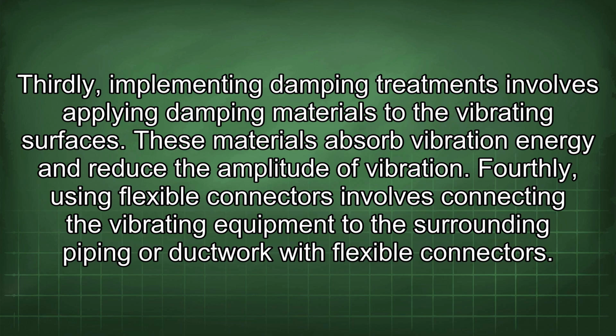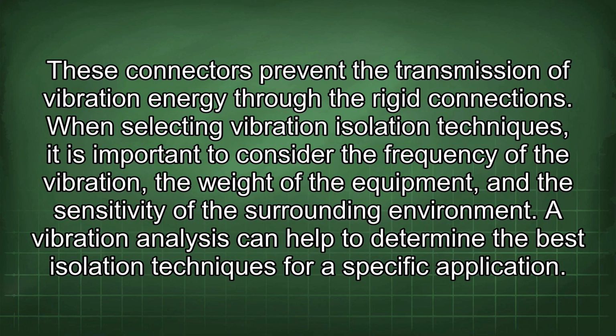These materials absorb vibration energy and reduce the amplitude of vibration. Fourthly, using flexible connectors involves connecting the vibrating equipment to the surrounding piping or ductwork with flexible connectors. These connectors prevent the transmission of vibration energy through the rigid connections.